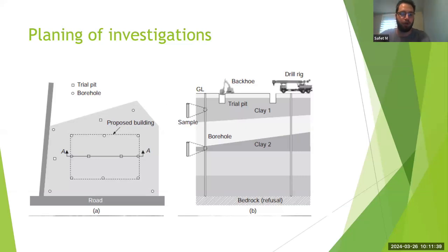So every time you would know the boundaries of the building. Depending on the requirements of the standards your country is using, you're going to place boreholes or trial pits or whatever kind of investigation you want on a plan where the proposed building is. The depth of the boreholes is going to be defined by you, but you need to meet the minimum requirements that standards would require, depending on the building or whatever structure you're going to build.